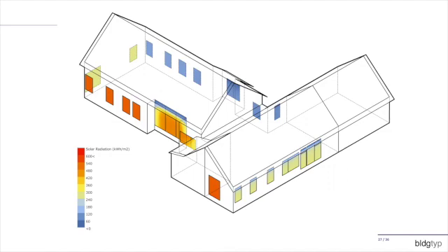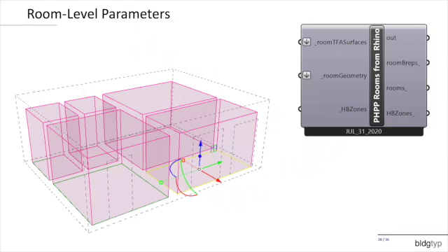In any event, we're using these methods internally, and I think it gives us a lot of information. This is a graphic from a client report. It allows us to show our clients, who are often other architects asking how to make better designs, a lot of very detailed information, and we can make, I think, smarter decisions around shading and overheating risk, etc. And obviously doing things like dynamic energy modeling. It's going to give us a much better window into things like overheating risk of critical rooms than the single zone PHPP ever could, right? So that's going to be really impactful and powerful as part of our toolkit here.